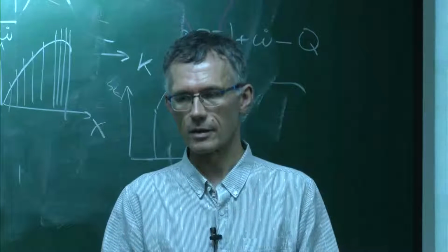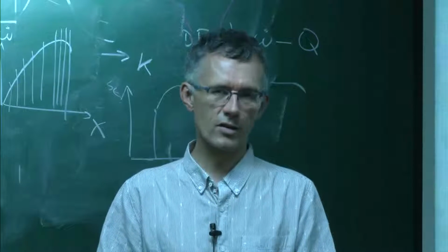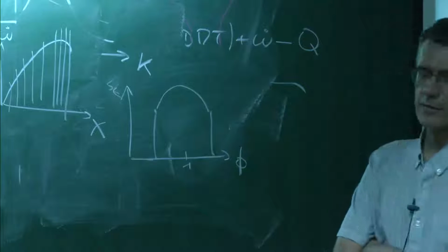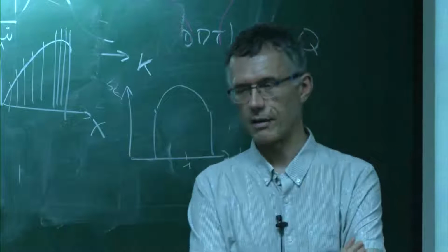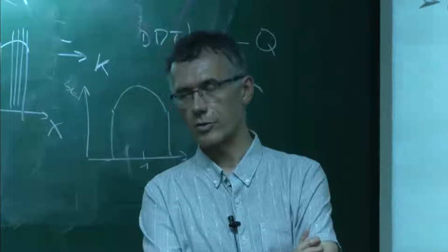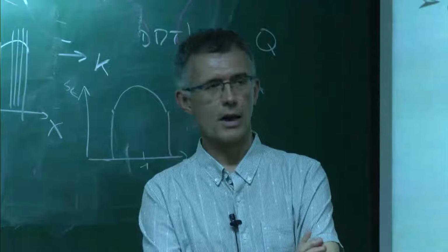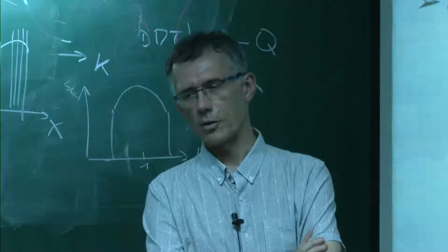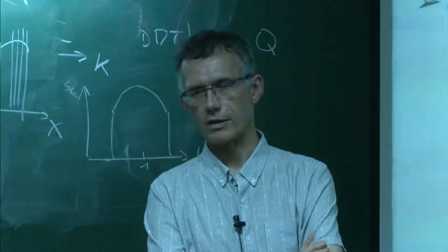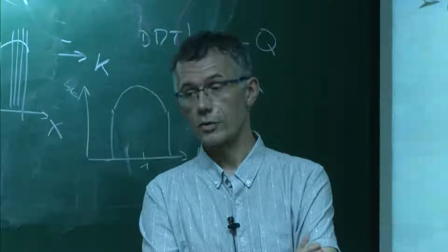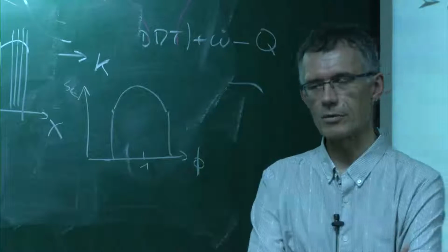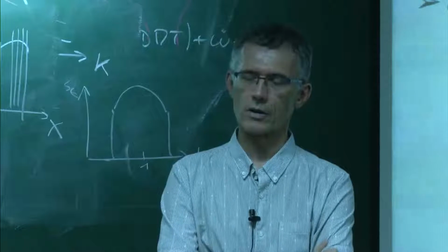And also linear eddy modeling. Okay, the linear eddy model I did not describe. It is really a different view. You need to solve a 1D problem per cell in your computation, and that's supposed to account for mixing and turbulent combustion at the subgrid level. I think again it's a complicated model for many chambers. It's very expensive, and Georgia Tech is doing it now, and Sandia keeps doing it, but that's about it, and not that many people try that. I think it's a complicated model to run.